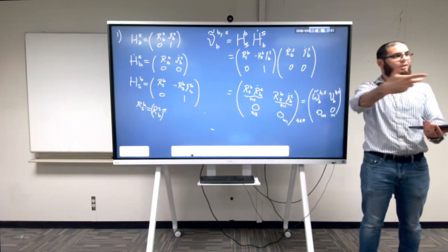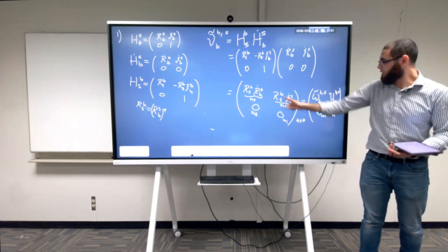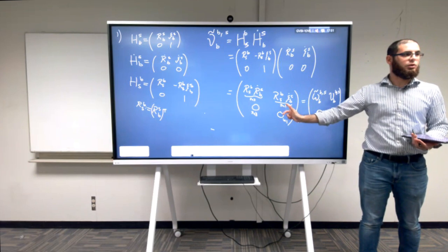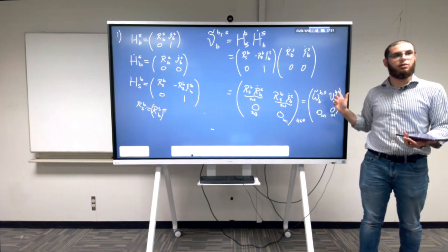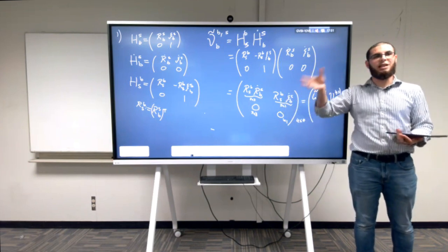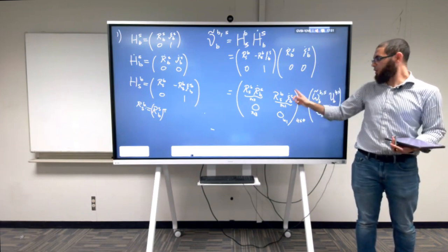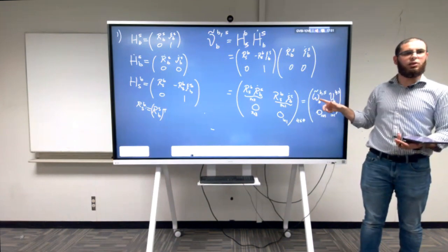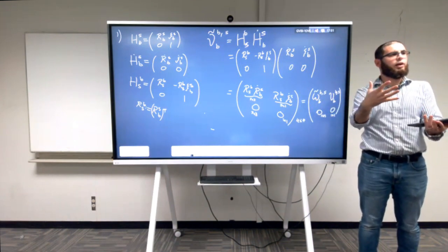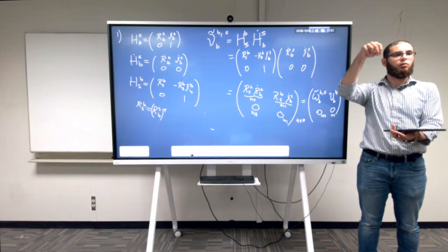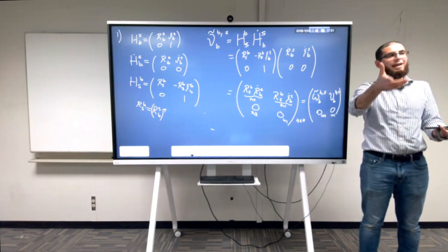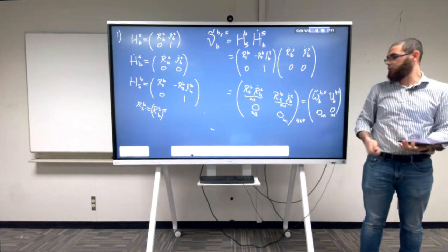If you're rotating and at the same time you're moving, you get this coupling between velocity, and the velocity is not the rate of change of position. Of course, if this is 0, this is 0. It makes sense, right? Because this rotation matrix is the linear map between R3 and R3. And this angular velocity written in a skew symmetric form is nothing else than just some fancy way to write a three-dimensional vector, which is the omega you're all used to, rotation around some x-axis and y-axis and z-axis, angular velocity.